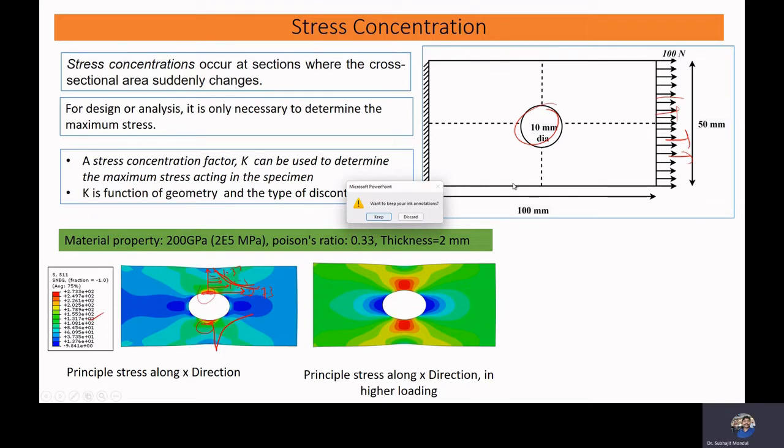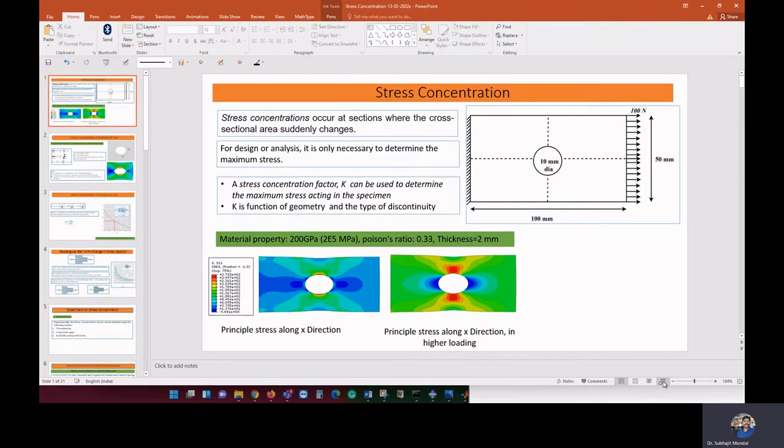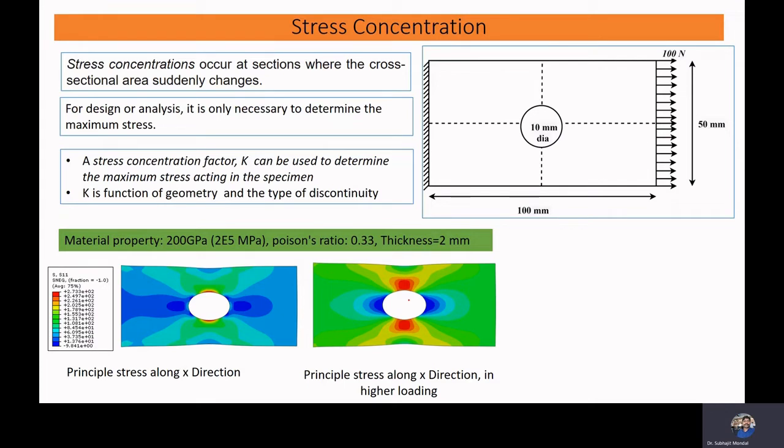So here what we have seen is the change in stress if we have a plate with a circular cutout and apply the load. This circular part will be elongated and look like an ellipse. There will be high stress concentration here, and if you go away from here, the magnitude of the stress varies like this. This colorful pattern shows the different kinds of stress we have. If we plot the magnitude, it will look like this. This is all about stress concentration